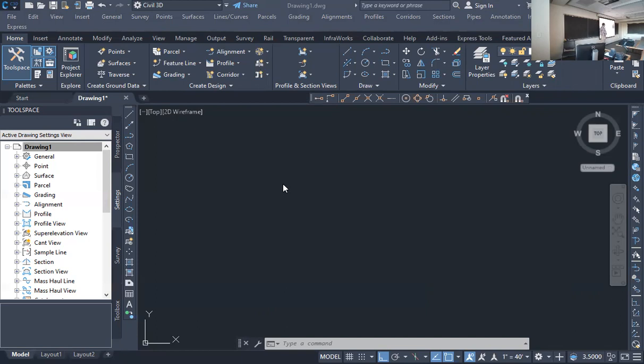Meters. What is S feet? Survey feet. Is there a difference between survey feet and international feet? Yes. Does it matter a whole lot for the surveys that you're going to be doing? Probably not. Translating these out to miles and miles, yeah, it's rounding. It's how it adjusts, right? So you're in Pennsylvania State Plane Coordinate System, South Zone. Those are your coordinates, northern and eastern, right?